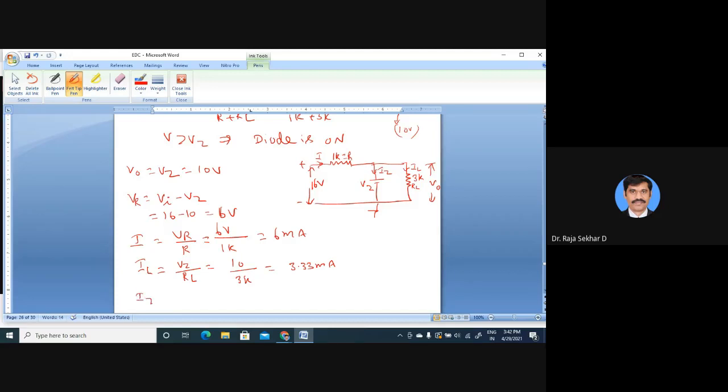Now what is IZ? I minus IL. I is how much? 6 milliamperes minus 3.33 milliamperes. We are getting 2.67 milliamperes. This is IZ.